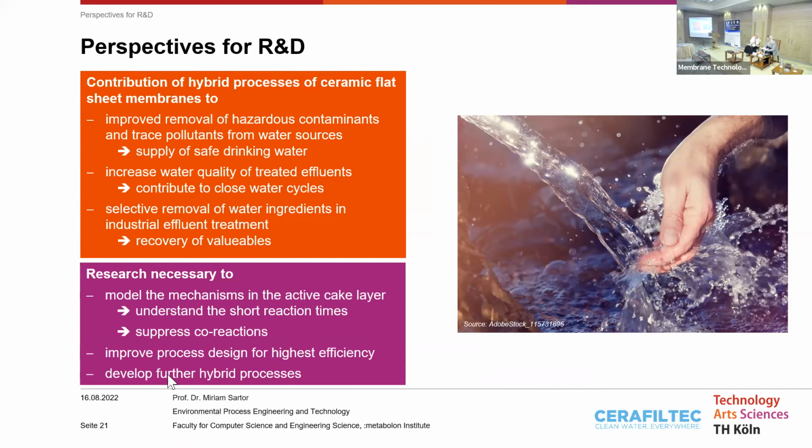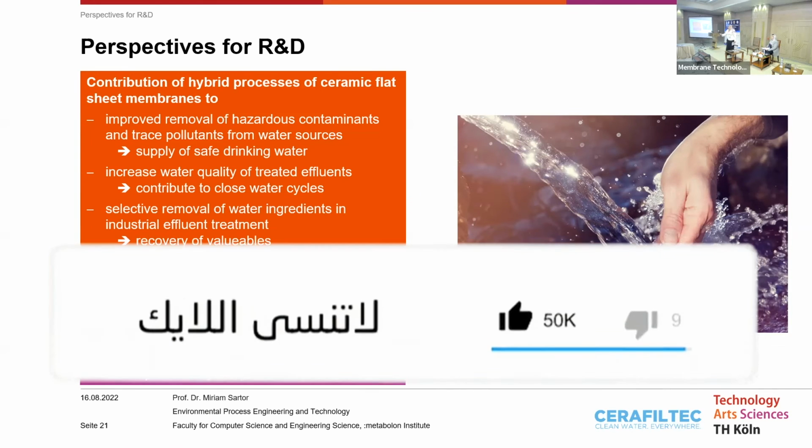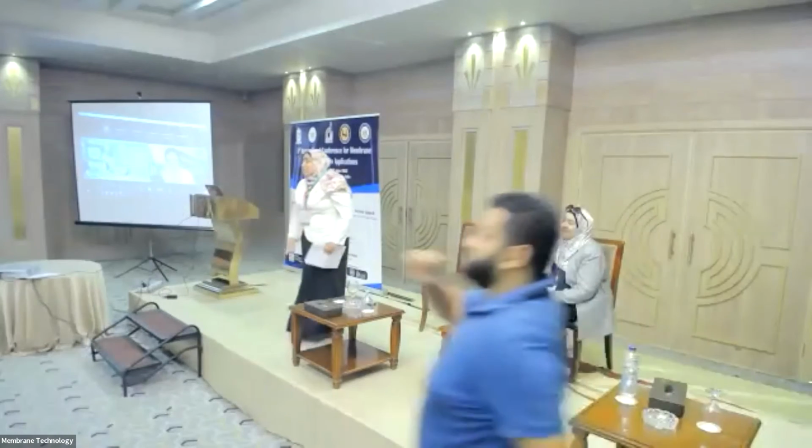Yeah, one question. Short question. How often do you have to do the backwashing? Very nice job. For this HMO process, they do the backwashing every 12 to 24 hours. It depends on the loading capacity and on the contamination, but normally it's approximately around 12 hours.